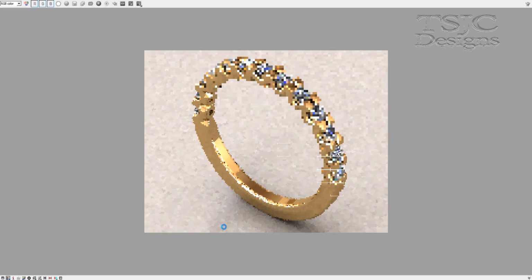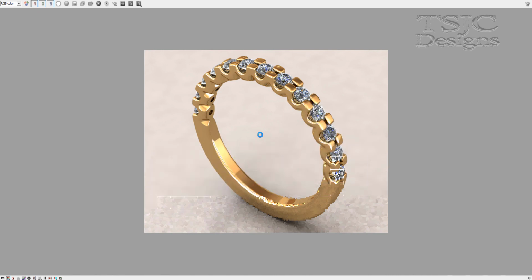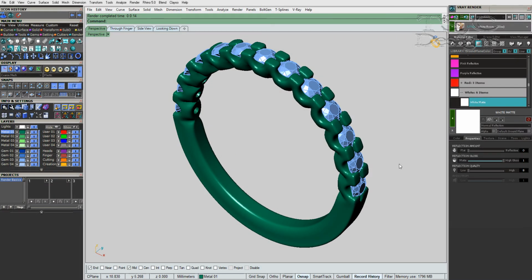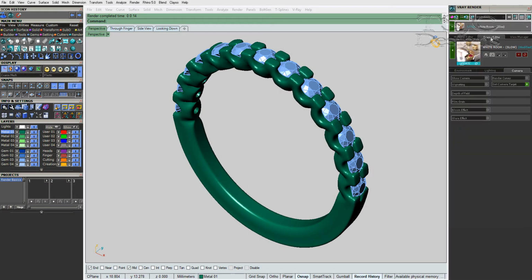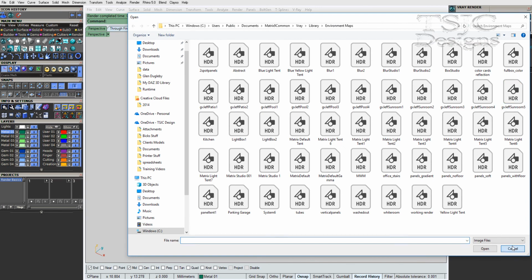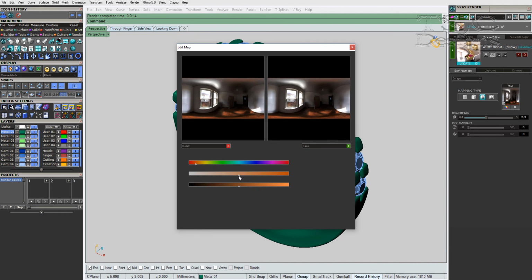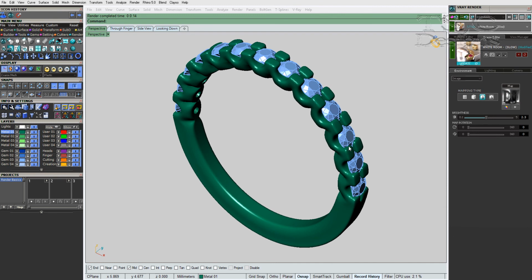So it's got rid of that reflection, but it's still got an orange tinge to this, which is from the HDR effect. Which isn't too bad. So scene, environment. So this is your environment. Let's click this little button here and desaturate it so it's black and white, and save that out and render again.